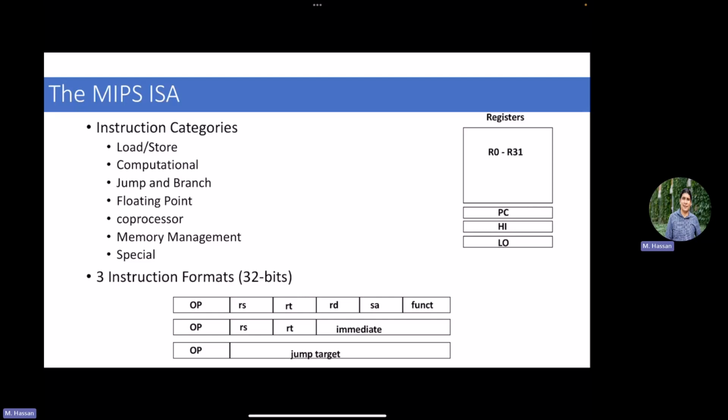What is the RISC instruction set? It said, okay, this whole mess of allowing one instruction to do whatever it wants and so many operations is complicating the hardware a lot and making it non-modular. So instead, the philosophy of RISC instruction sets in general, whether it's MIPS, ARM, PowerPC, or something else, is that every single instruction does a single thing, right? If you need to execute multiple operations, you have to write multiple instructions.